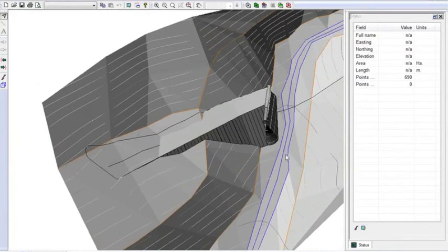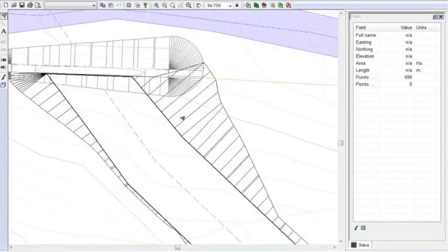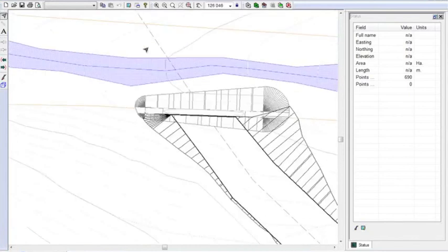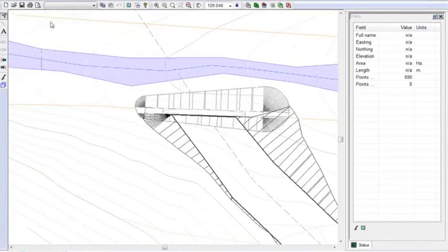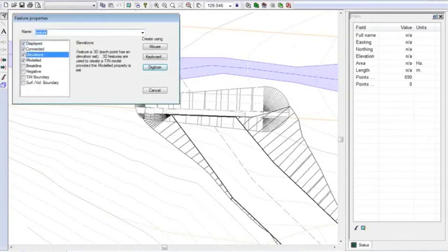Now we've got two surfaces. Sometimes it's nice to actually show all the original surfaces without merging them, because you get more information in your cross-sections. Like, for example, now if I merged this, I wouldn't see the difference between the ballast wall and the road fill. But now, if I take a cross-section here, so I'll create a new feature, which is draped, call it section.